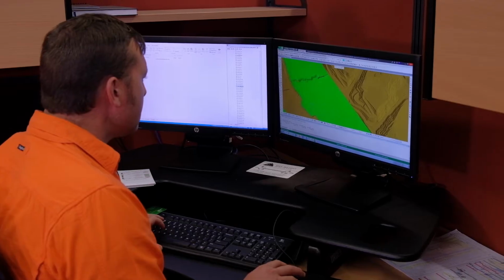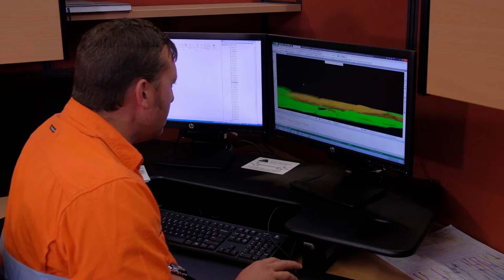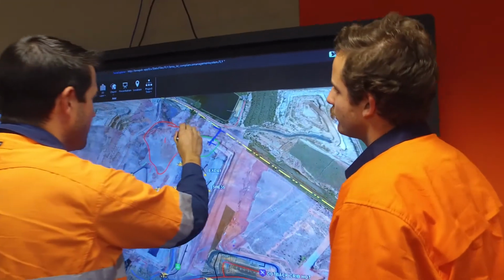If mine designs don't conform to the geotechnical design standards, the mining engineer should modify the design accordingly or discuss options with the geotech to achieve a safe slope design. As-built and mined-out surfaces are used to build slope stability models.